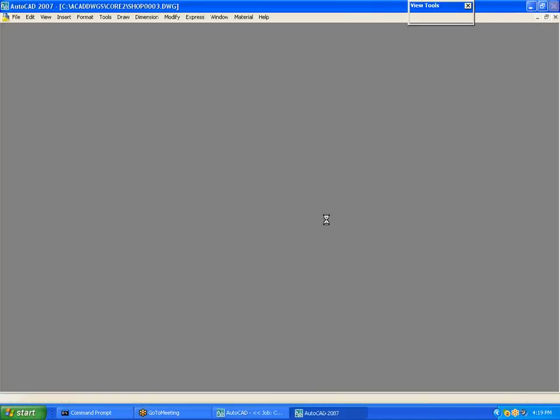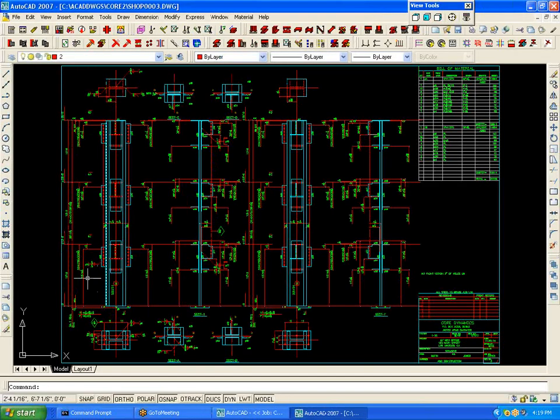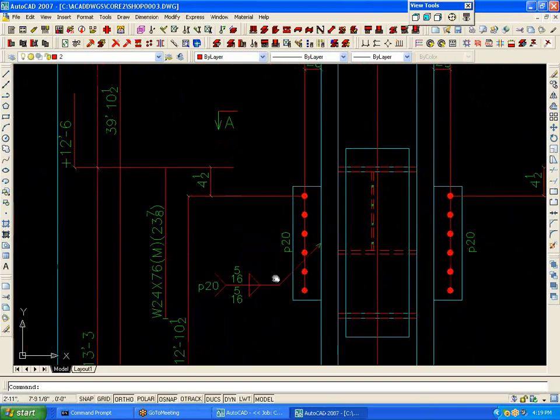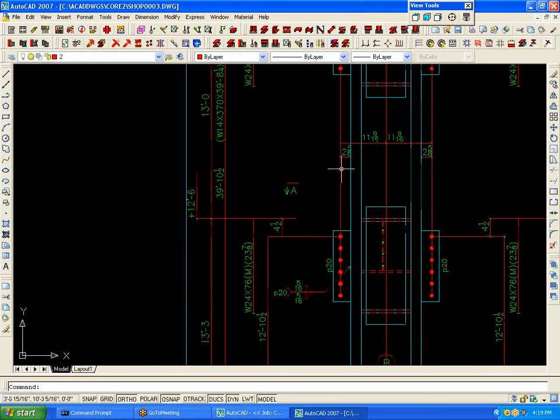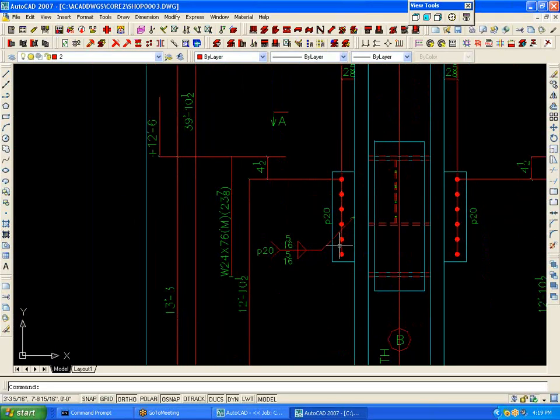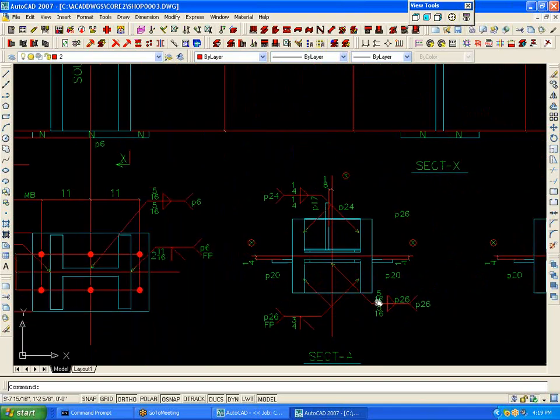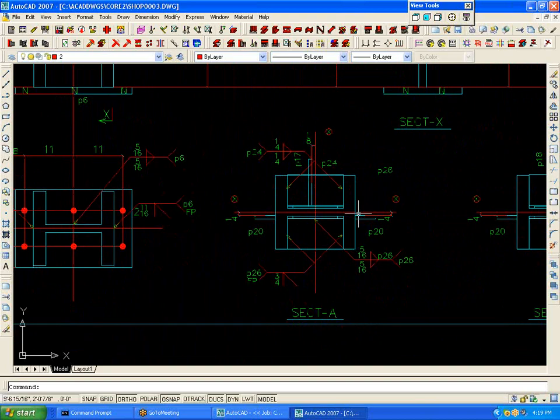Now since the plates are pre-drawn on the CM sheets, we don't have to show you all those dimensions again. All we have to do is locate it for you, make sure you don't put the plate on backwards by giving you that dimension, show you how to weld it or bolt it, and give you the piece mark, and cut a section if it's necessary. Now this is a raw drawing right out of the system, so there will be a little bit of cosmetic overlapping, but compared to other systems, these drawings are exceptionally clean.